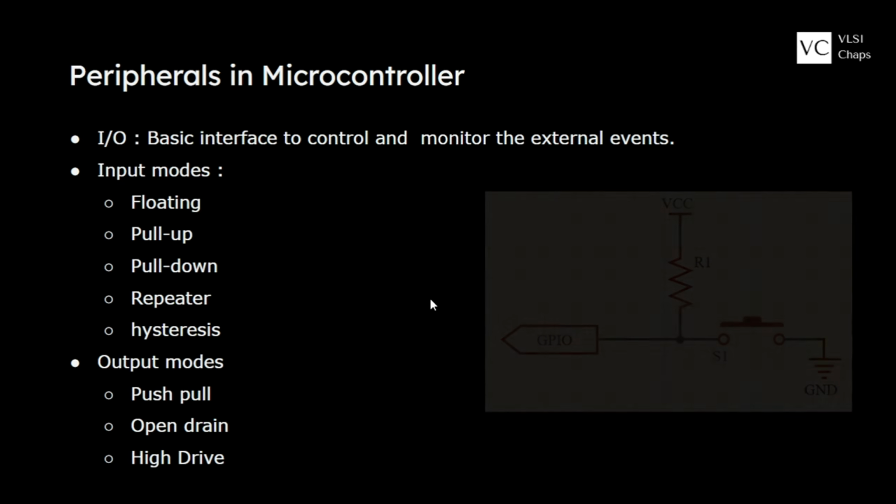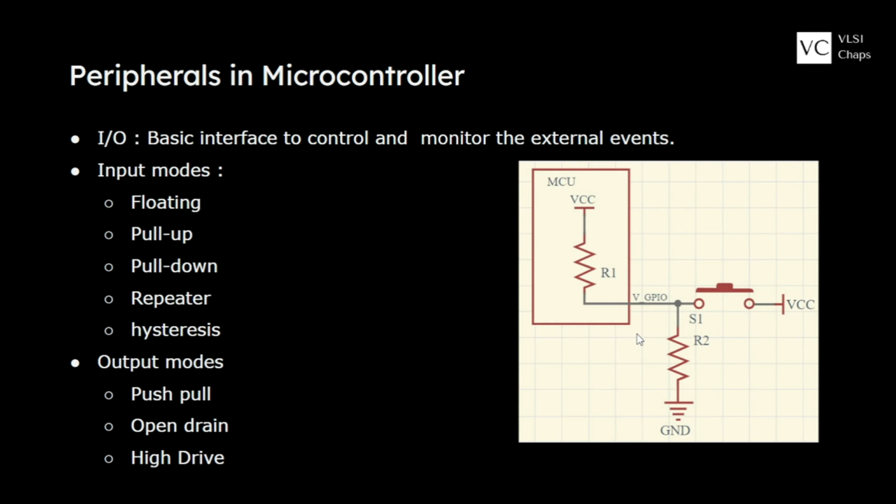Likewise, if we talk about pull down, then its initial state will be low. It will directly fetch the power from the ground. It will have a low state by default. Once I push the button or an external event is triggered, it will finish this loop from VCC to ground and get the whole state complete.